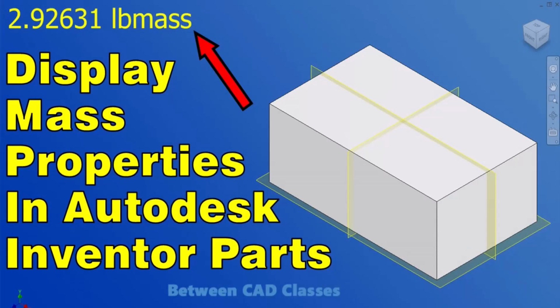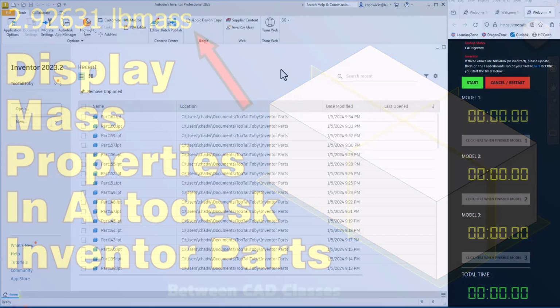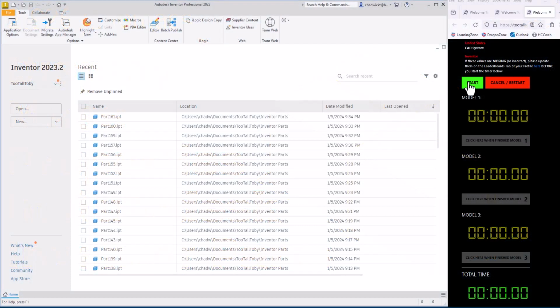In the challenge, the way that we show that we created the model properly is by showing the mass properties. You can do this by opening up the iProperties dialog box, but I decided to set up my templates in order to display the mass properties in the upper left corner of the screen. If you would like to learn how to do that yourself in Autodesk Inventor, once again, stay tuned to the end of the video, and I've got a link to another video that will show you how to do that. Let's now take a look at my submission.